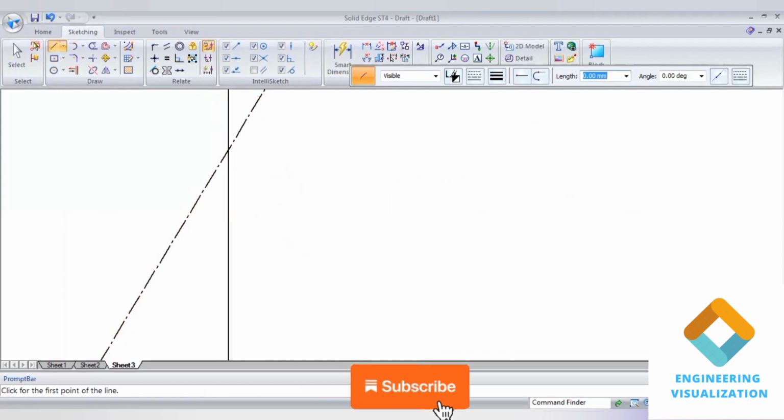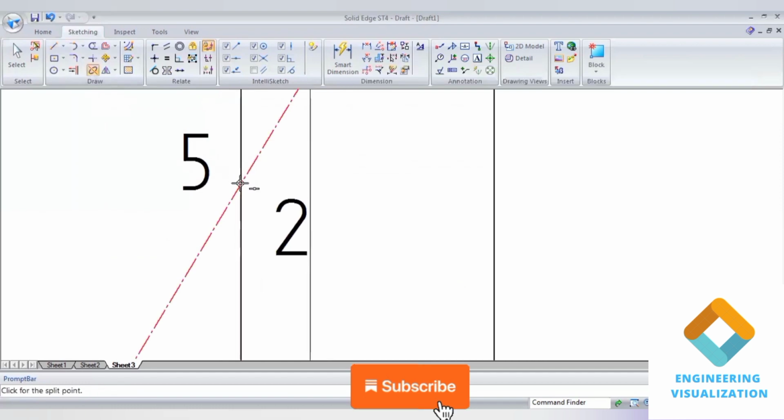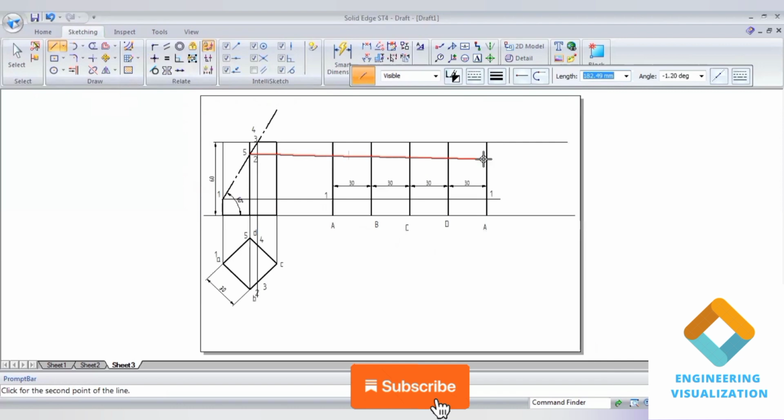Points 2 and 5 are on the same point, but I'm not getting the intersection here, so I can use the split command to get the exact point. I'll go to the split command and split it exactly where the section plane is cutting. Okay, so now I'm getting the exact point. From here I'm going to project it up.